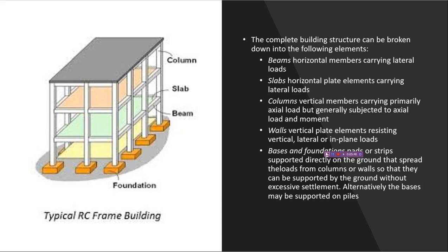So what a load bearing wall can do is avoid the use of columns, because columns tend to be bulky. A reinforced concrete wall is less bulky. So there is the option, but later on, if for example the owner perhaps wants to do renovation, it is a very hard structure for you to demolish. That's why in Malaysia we lean more towards reinforced concrete framing.